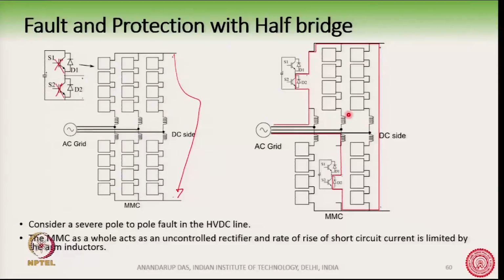Okay. The MMF which is getting impressed is very high, and so usually these inductors are made air core, because air core inductors are very hard to saturate because it is air. So, there is no iron, no amorphous core, no ferrite core involved in case of a low voltage. If we use an amorphous core, it is very easy to saturate it, but if we use air core, it is very difficult to saturate.